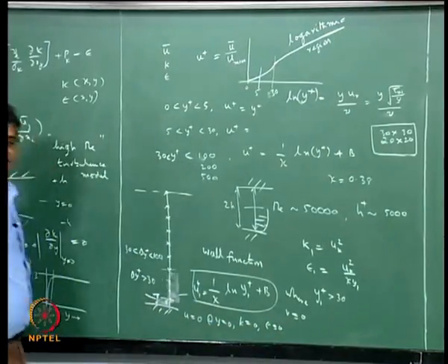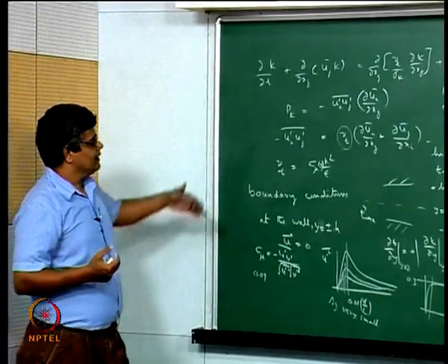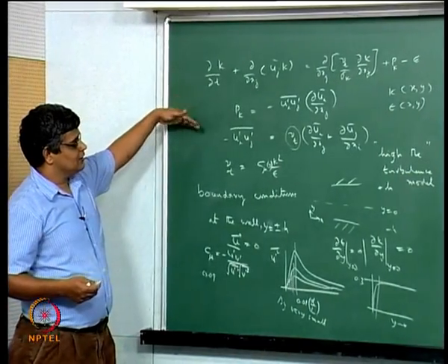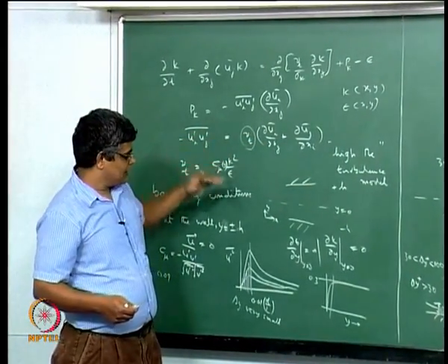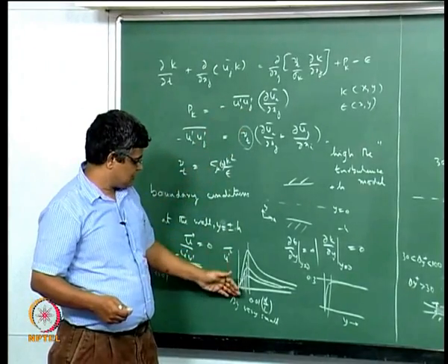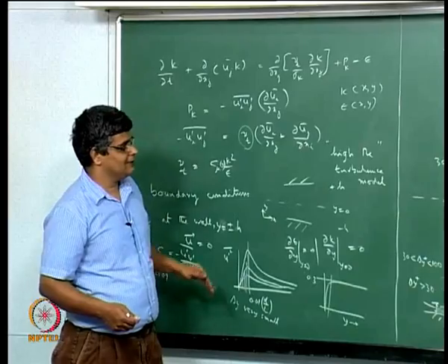So you have the natural boundary conditions for such models, those turbulence models which make modifications to the standard high Reynolds number turbulence model in such a way that you take account of the anisotropy and the damping of turbulence close to the wall.